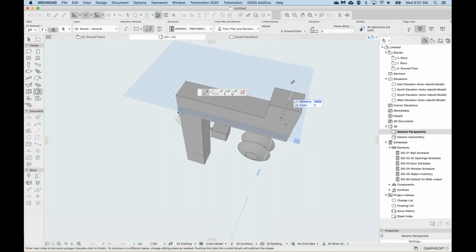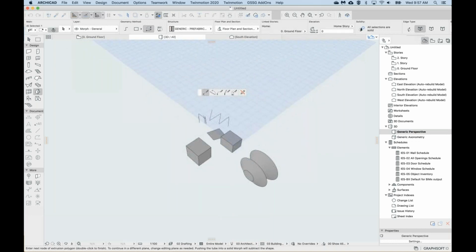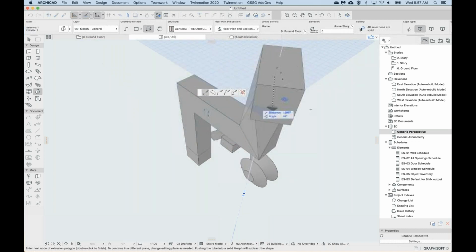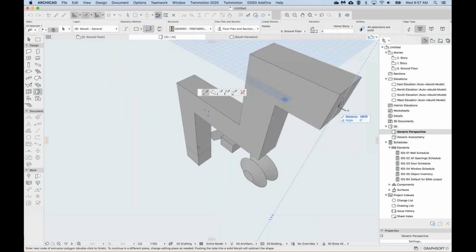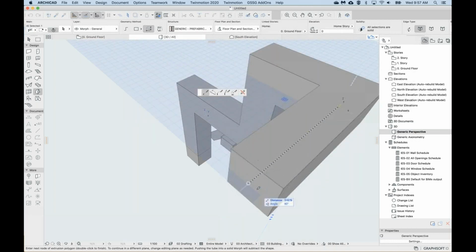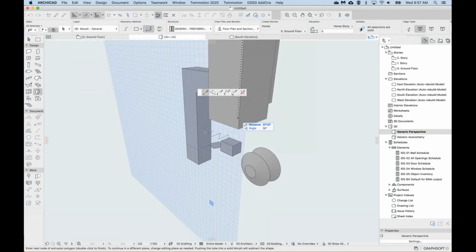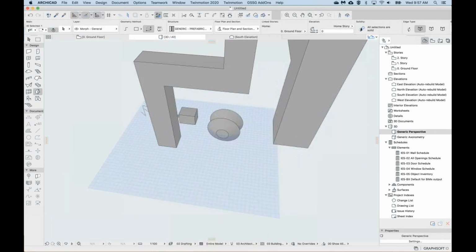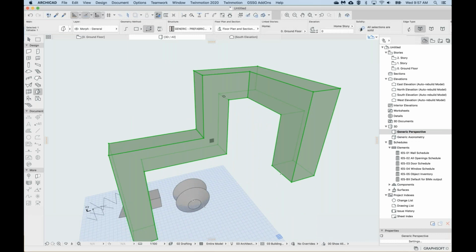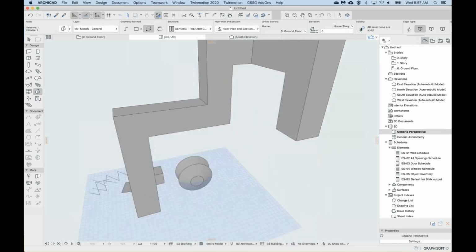Then I'm going to find the Z and then hold Shift, and try to find another one. I'm just trying to find the axes when they turn yellow. And when I want to finish, I right click OK to finish. So now I've extruded along a polyline.